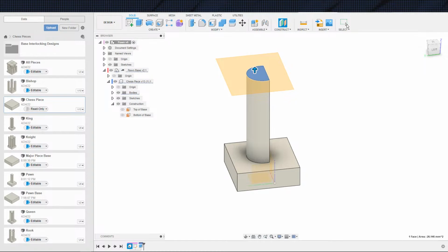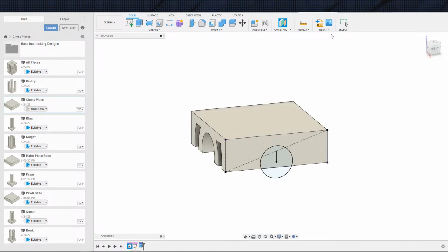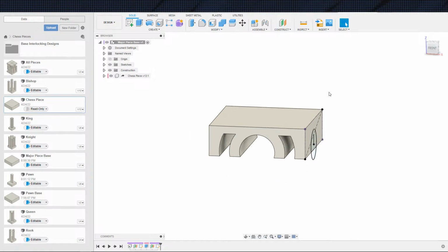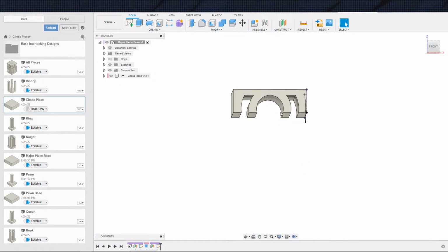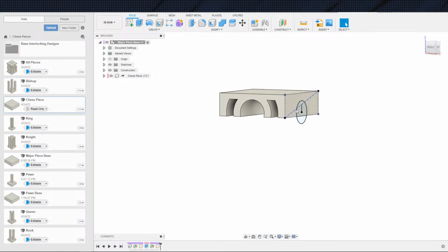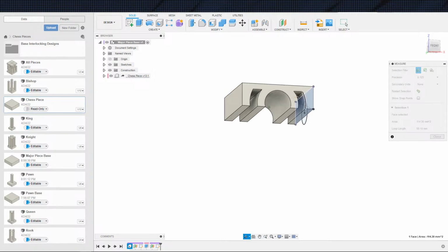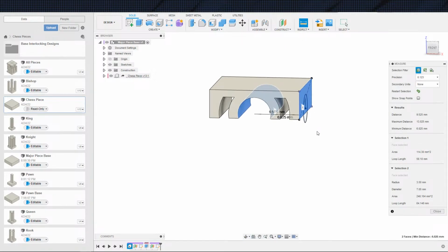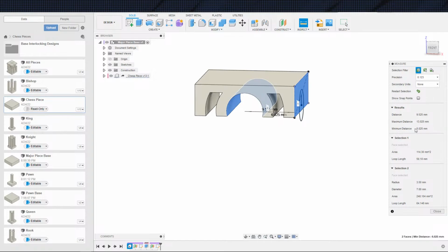So this becomes a little bit of a balancing act, because let's look over here. You see where this clip is right here? So between this inner shell, because I can extrude all the way through, and that outer wall is my maximum distance. So the minimum distance here is 6 millimeters. So actually 6 millimeters really isn't that bad. So we can have a pawn head up to 6 millimeters tall. So let's go ahead and change the pawn height.